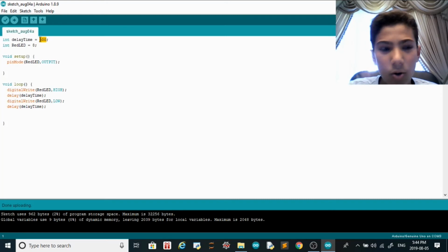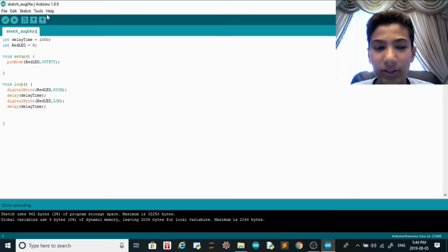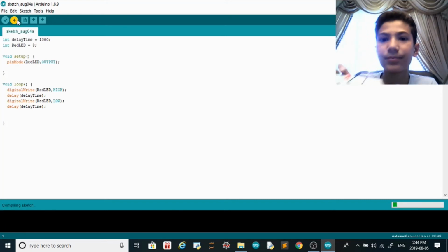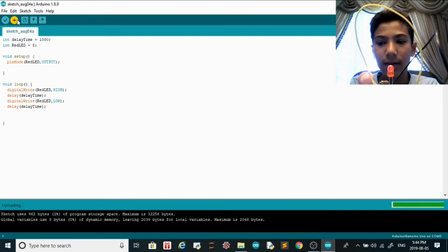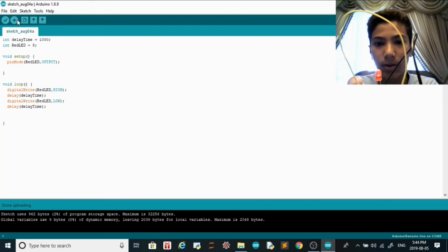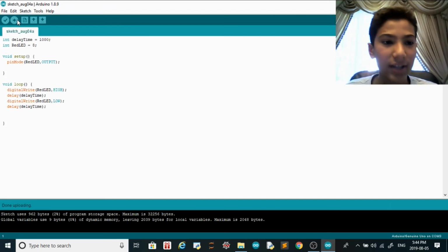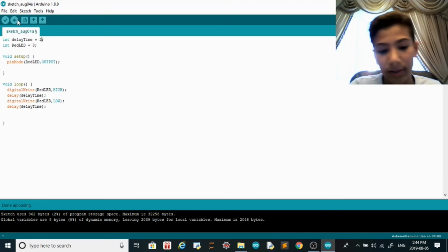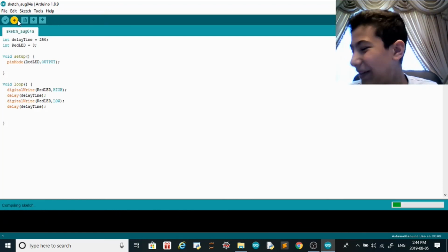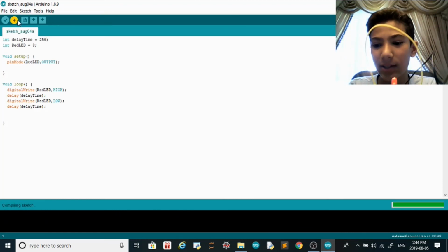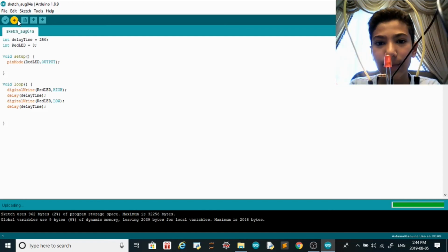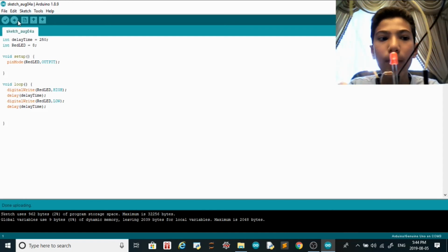So now if you want to change, let's say I want to blink 1000, which is 1 second. Turn it on. And it's going to stop. And now it's going to do 1, stop, 1, stop. So now it's much slower because I put 1 second. But if I want to go super fast, so 250 milliseconds. Now it continues because you need to upload. Go super fast.